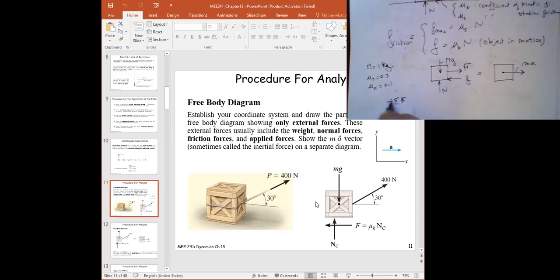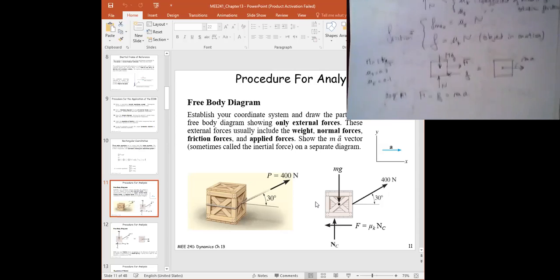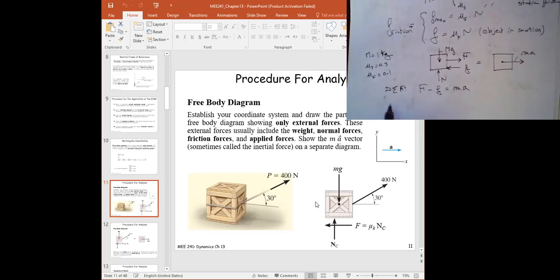If I sum the forces in the X direction, I'm going to get F minus f equal to MA, right? And then I'm going to use this to find the acceleration. Deal? Okay, let's say F was equal to 0.1 Newton. What is the value for the acceleration? We need to know the friction, exactly.